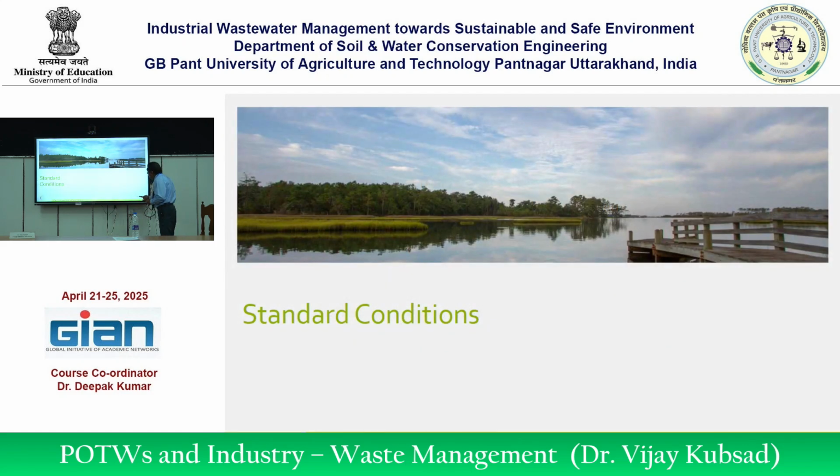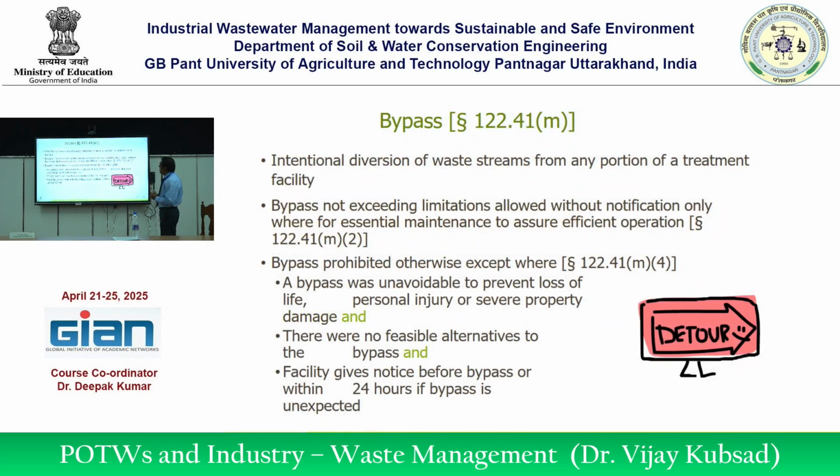Standard conditions and bypassing. Intentional diversion of waste streams from any portion of the treatment facility. Bypass not exceeding the limitation is allowed without notification. Bypass is prohibited, otherwise, except if a bypass was unavoidable to prevent loss of life or personal injuries, and there were no feasible alternatives for this bypass. When you do it, the facility gives notice before the bypass, or within 24 hours if unexpected. These are the regulations for how you should manage these kinds of landfills.